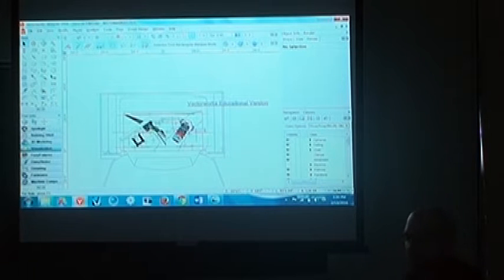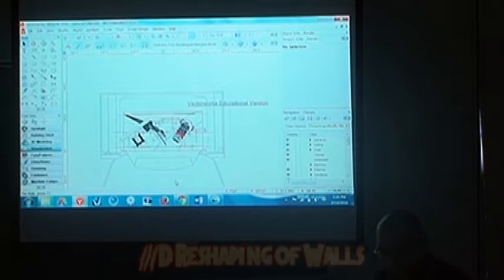And then one other thing is the marquee tool. So if you drag a window around something, anything contained inside will be selected. If you hold Alt when you do that, anything you touch will be selected. So that's another way of grabbing objects that you can't, for some reason, entirely contain without getting other things you don't want. You could just touch them by holding Alt. So that's that. All right, let's jump into the interesting stuff.